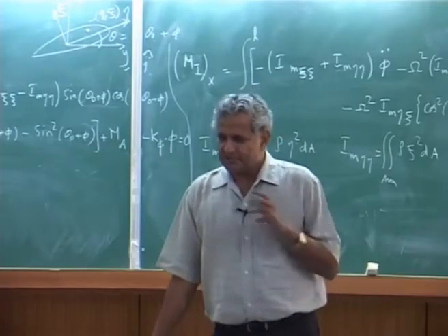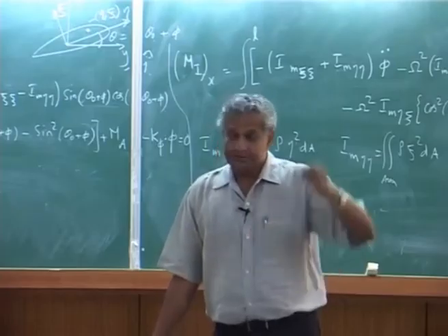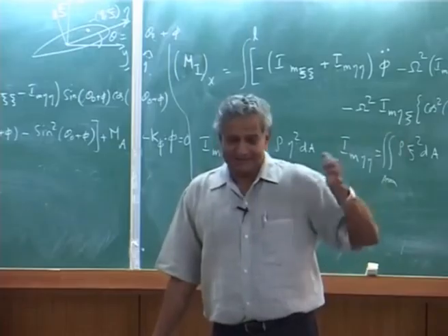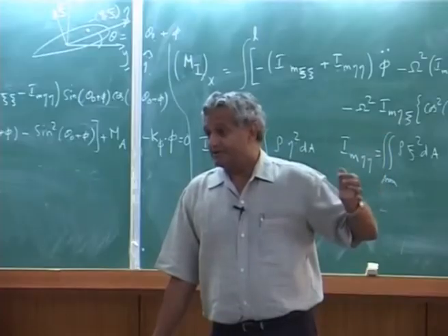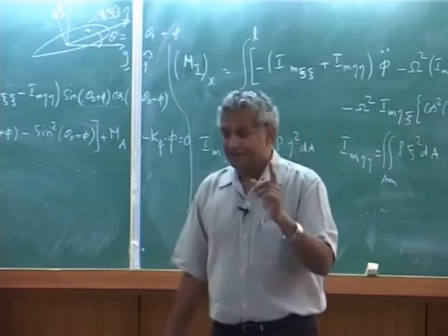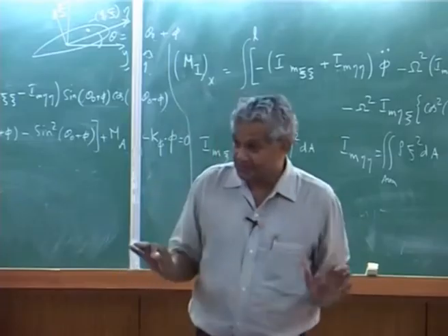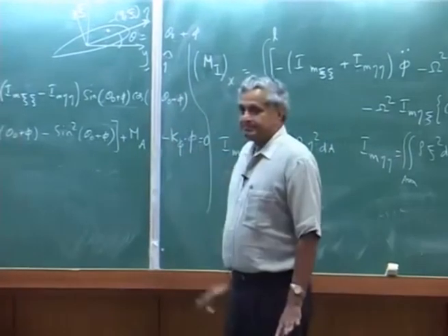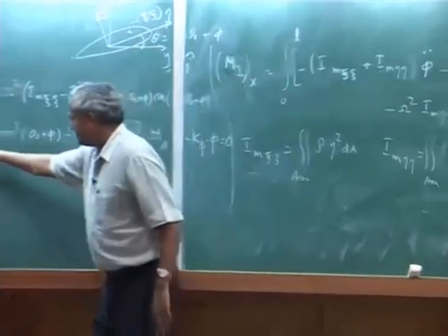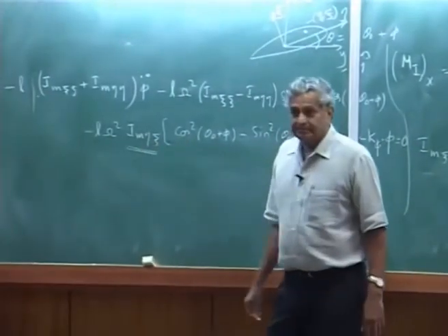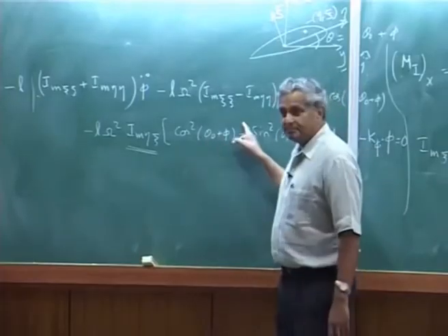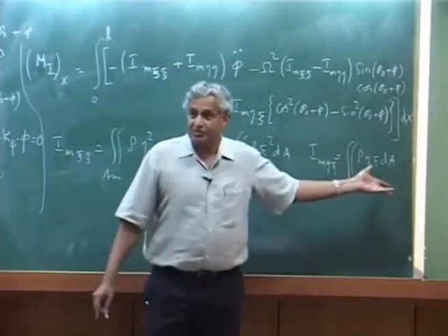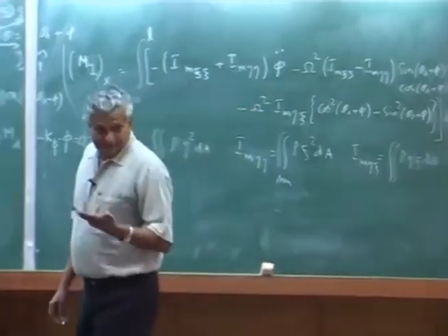Because if you want to be systematic, it is better to start from scratch, so that your fundamental principles are clear: position vector, then velocity, then absolute acceleration of a point which is in a blade which is rotating, then you will not make any mistake, okay. Now, if you derive that, this is my equation. Suppose you say my cross section is symmetric, okay, symmetric cross section, then this term drops out, because I m eta psi will go to 0, okay.